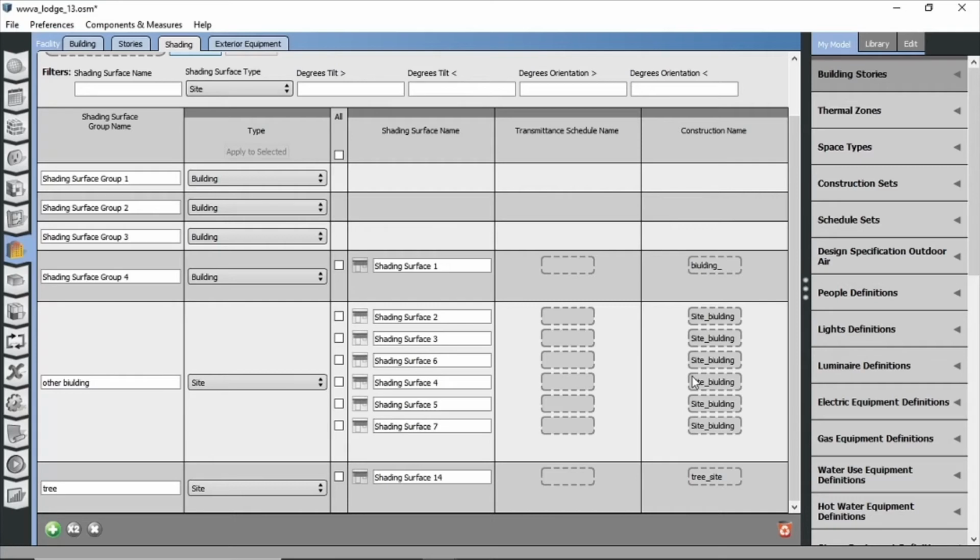The tree does not have its full foliage every day of the year. There is a period that the tree has a certain transmittance value, and another period that has a different transmittance value. This variation can be described to the program so that it implements these conditions in the simulation. Let's now work out this transmittance schedule for the tree.